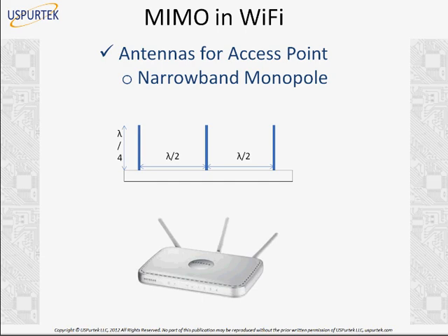Okay, this seems to be a specific problem in the UK. Why a problem with TV frequency in the UK? Okay, for LTE. These types of problems happen because the LTE frequency allocation is based on a countrywide basis. When we go to the LTE slide, I'll show you what frequency bands are available in different countries. Sometimes they might overlap. If it is very adjacent to a TV allocation in that country, it might interfere.